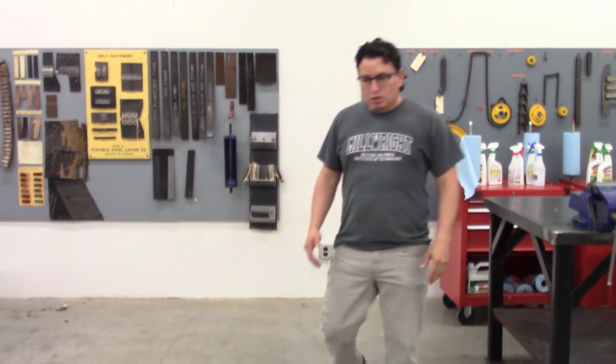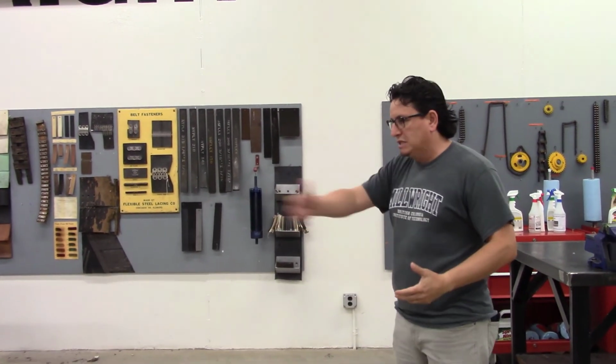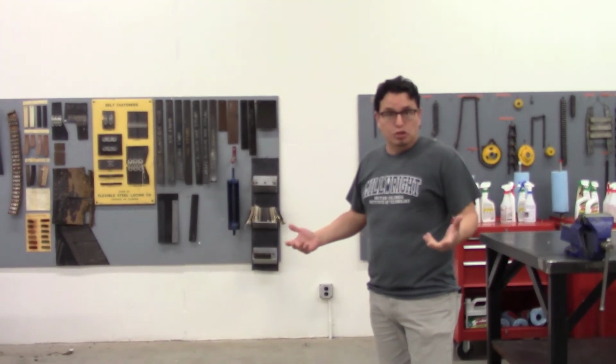All right, now that we have some more information on what we're going to do, we know about base plates, we know about soleplates, we know about a certain equipment, a certain machine, pump, motor. Our next step would be to find a place in the shop where we're supposed to be laying it down and proceed to lay out your lines. One of the first things you do is take measurements from the machines itself, record the measurements, and then proceed to transfer them to the ground.